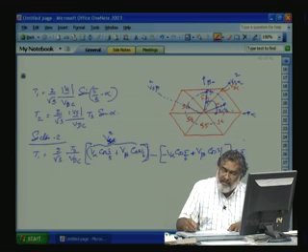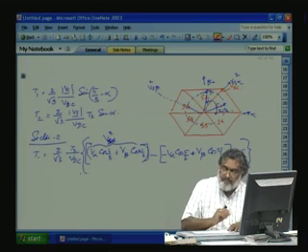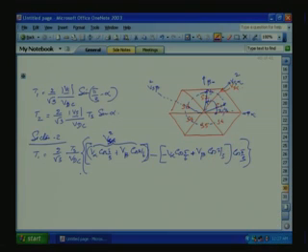Okay. This is our final equation. What we did: T1, T2 in any sector depend on the sampled reference phase voltage Vs along the start of the sector and the one perpendicular to that, that is Vs alpha and Vs beta. But in sector 1, Vs alpha is equal to our alpha component, Vs beta is equal to beta component. Now, in every sector, the Vs alpha, Vs beta has to be transferred to our fixed alpha beta component by appropriately taking the components of the Vs alpha and Vs beta.